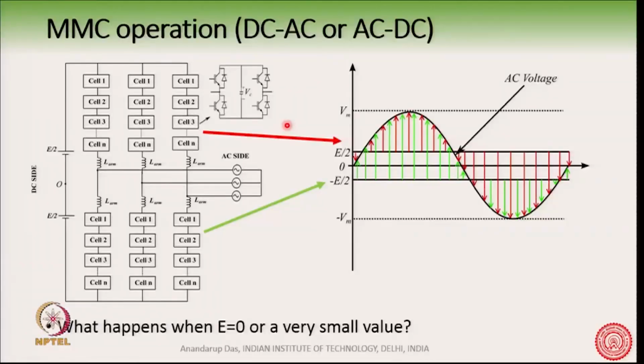But at least for the time between when this short circuit happened and when the AC side breaker opens, say about 3-4 cycles, 80 to 100 milliseconds, during this time when the circuit breaker has not opened on the AC side, it is possible for the converter to prevent a very high rate of rise of current during a short circuit condition.